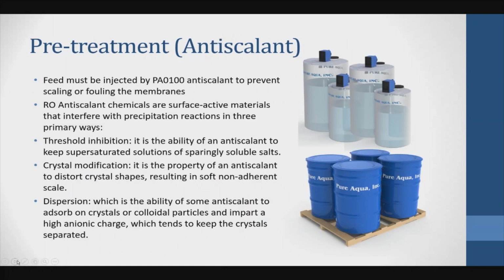Now, we talked a little bit about the anti-scalant and the benefit of it, and what we said is that the idea of the anti-scalant is very simple. It makes the surface of the membrane slippery, so the calcium and magnesium and the other particles would not stick on the surface of the membrane.